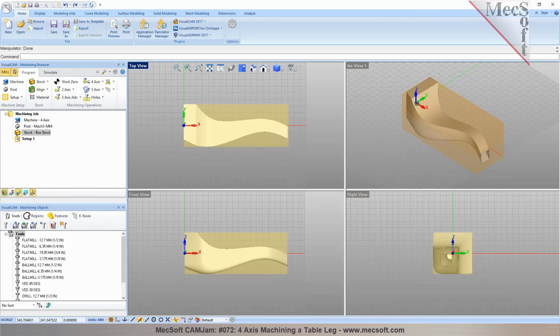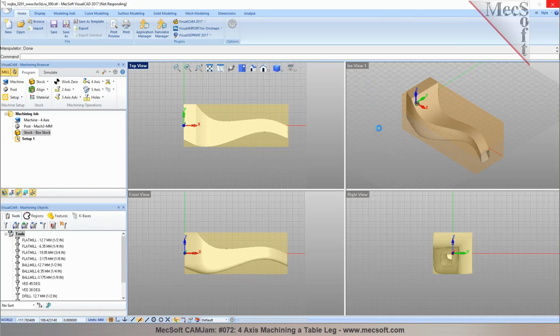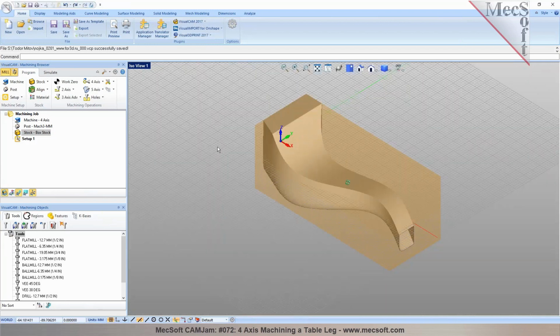So first I'm going to just hit save to save off the work in here. So we'll save the part and then we'll continue programming it. Any questions so far? So now we're going to go ahead and program some toolpaths. The first step is you need to create some roughing operation where you're going to be roughing it out in levels, where you'll be basically going from the initial stock that you have down to the actual part itself. So that would be done using an indexed operation.